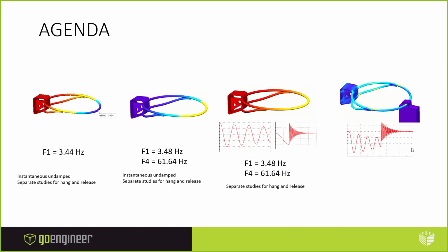To summarize, here's our linear dynamics study. We're using those same frequencies, so you see the frequencies aren't any different. We're just piggybacking on the results we got from the frequency study to run this study. Here are those same frequencies, and you can see the results of the one I just ran, but also one where I do a release and see those vibrations. You see how quickly the energy is lost in those higher frequencies. That 2% does quite a bit there. But these have to be two separate studies, because I cannot turn off mass in the middle of a study.